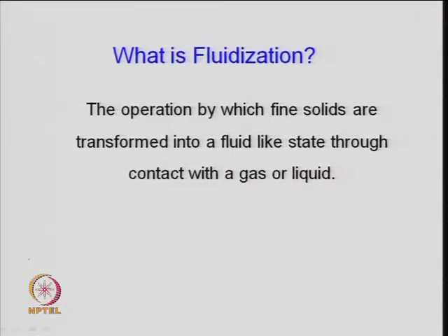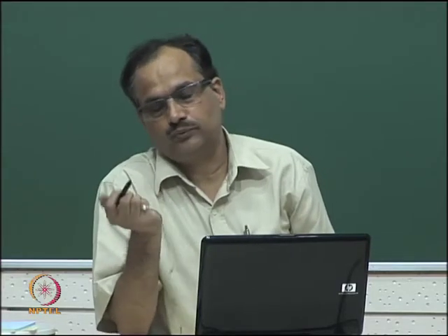You know that if it is a packed bed and you give gas flow at different velocities, then up to a certain superficial gas velocity there will not be any kind of bubbling, or the bed will be static, right. The solids will remain in a stable condition in the bed, but when you increase the velocity, there will be more and more voids, and then the bed starts to reach a fluid-like state, or there will be a kind of bubbling inside the bed.